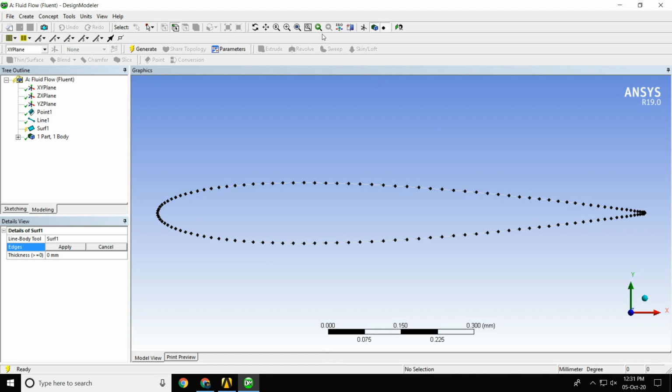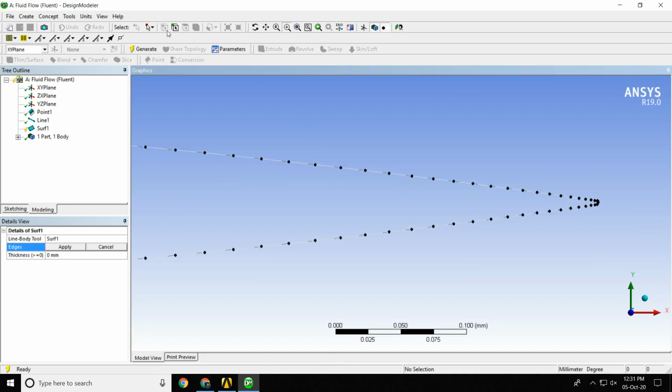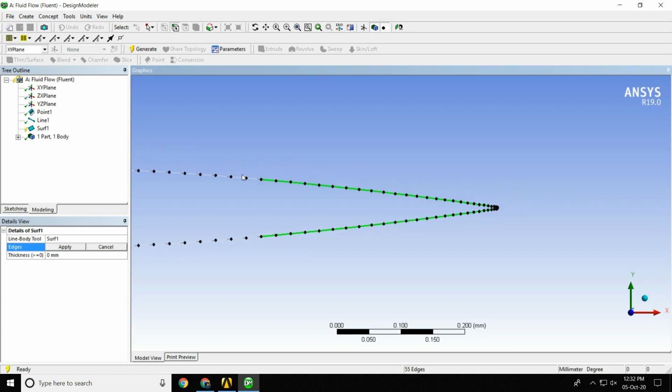So what you do is come for this end first. Okay. Select edge, hold control. For this, hold control because it will not continuously draw. Therefore, hold control. Because if you let go of the left button without holding control, it will start from the beginning. So hold control.